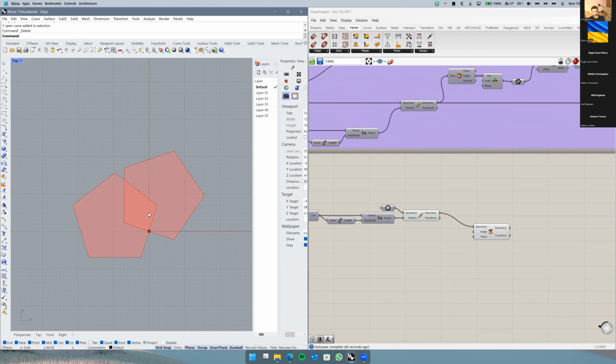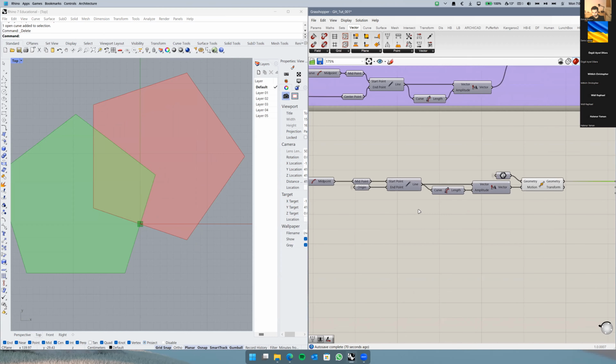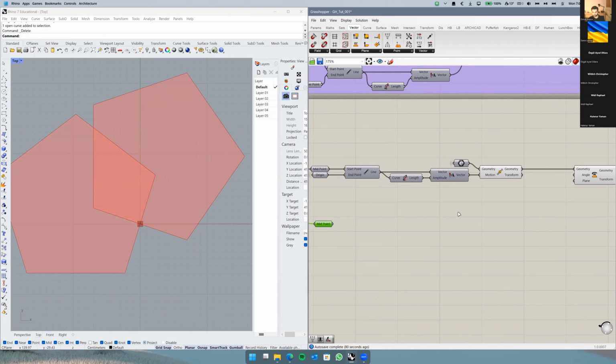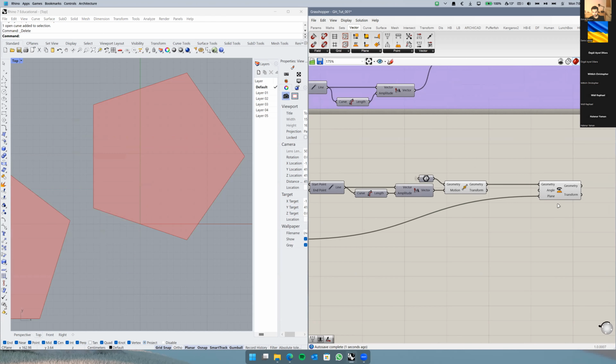I want to rotate this object so this line sits on this line. I need to take the middle point again. So that's my middle point. So wherever I go, I can make it horizontal, that this middle point is my anchor point. So if I turn it 30 degrees, this side will turn 30 degrees as well. So I already have my middle point here. I'm just creating a copy of it. That's my anchor. That's my plane right now.